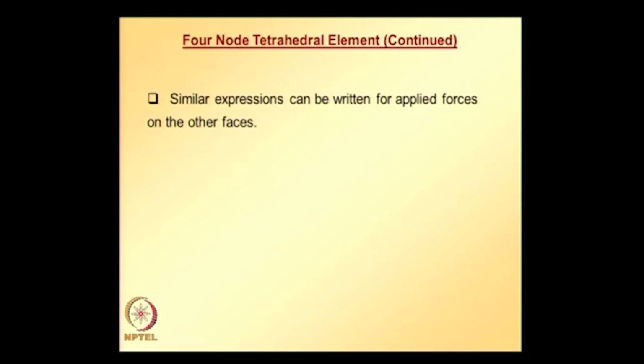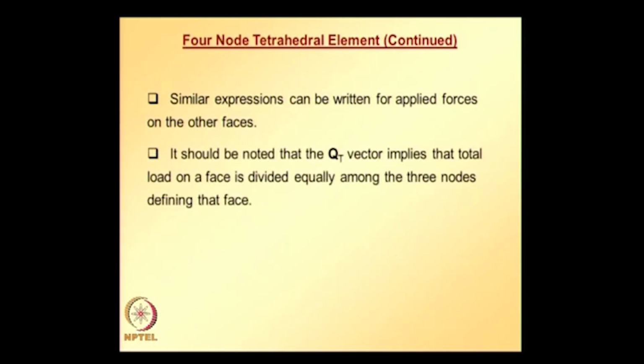And similar expressions can be written for forces applied on other faces. It should be noted that Q_t vector implies that total load on a face is divided equally among the 3 nodes defining that face. And body forces can be handled in a similar manner.